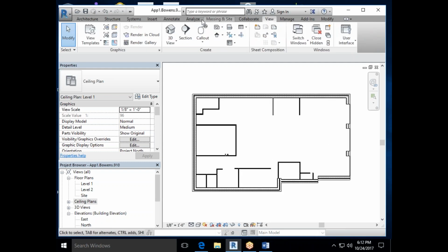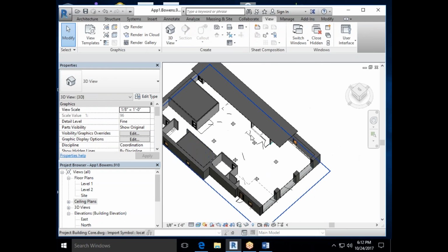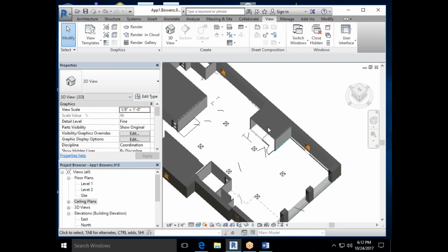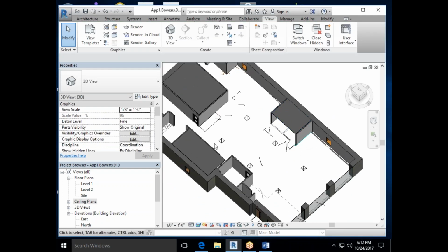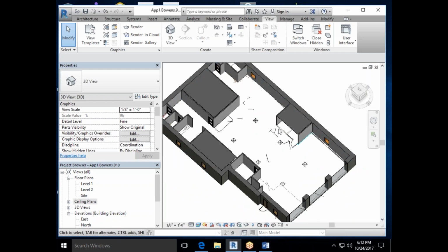So if I go to my view, and my 3D view, I had my big long cheater guy here, but you can see there he is on plan. So you can check with your 3D view from your 2D plan and make sure that you're getting all the rooms. It's better to just chunk it off. So you could do this whole big open portion as one thing, but little rooms do need their own roofs. Not this guy who doesn't really have a wall. He's probably part of the big portion, but this room, this room, this room, this one, they need their own ceilings.